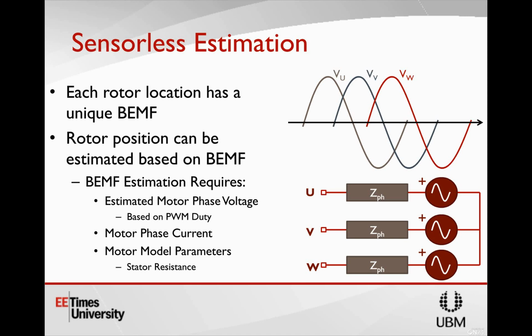To be honest, I never thought about this option. Interleaving is very frequent when we talk about power conversion, like DC-DC or AC to DC, and that helps to reduce the power losses on the transistors and reduce the input ripple current. I'm not sure this would work with the motor because you always have these three phases.